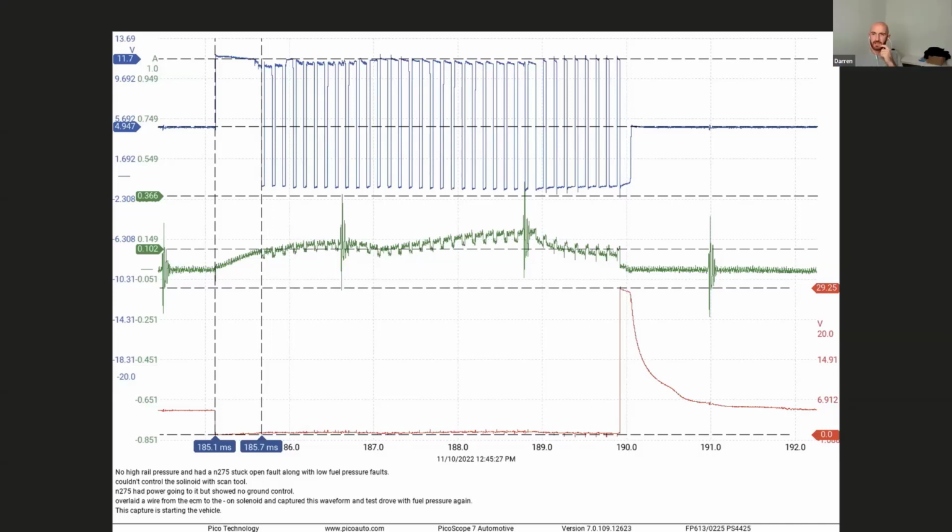I suppose it depends on how it's been pulsed, because we're PWM, aren't we? We are, yep. So if the other engine pulses the same solenoid at a different duty cycle, then it would be a different current, wouldn't it? I will go back and get voltage and amperage on the 17 Golf Sport Wagon to find that out definitively, because that's my parents' car, so I can have that whenever I want. So I will go back to the well and find that out for us. Yeah, in the current waveform, and also checking the physical resistance, because like I said, copy and paste at that level is rife. They all do it. Oh, yes, it is. And so I suspect that's what it is.